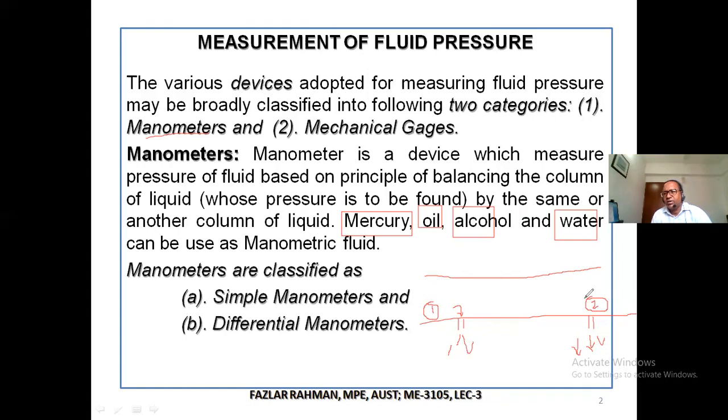Obviously at point one, the water leakage will be more, because it is losing some water, and then coming down, the kinetic energy of the fluid right over here is high, and over here will be less due to the frictional loss. So obviously the pressure at point 1, if I say P1, and at point 2, P2, in that case P1 will be higher than P2.